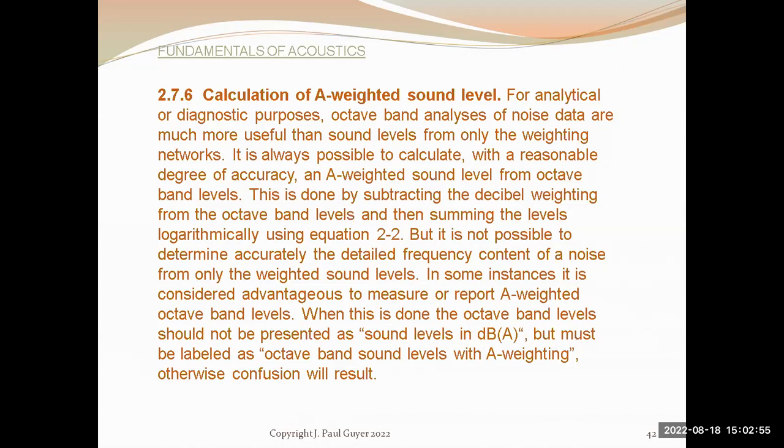So the methodology that you're using, ASTM, it might say sample the meter every 15 seconds, something like that, and do that for 20 minutes or something like that. And this will all depend on the environment that you are working in. Are you measuring sound levels of a freeway where cars are going by, or of a railroad line that doesn't have trains going by that frequently?